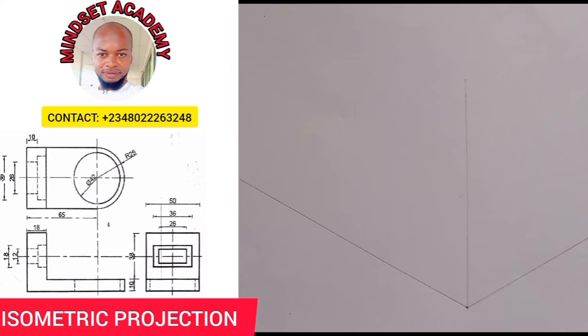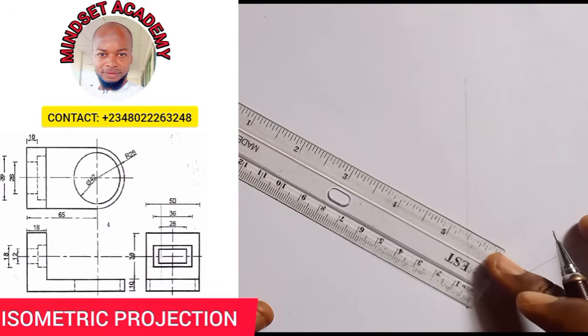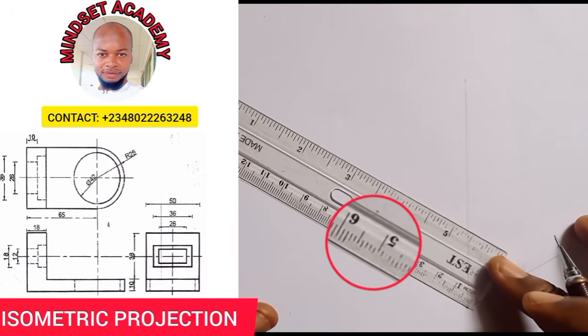The one on top of the elevation is the plan. The length from the beginning of this point to this point is given as 65. Then the radius of this arc is 25. So 65 plus 25 is 90. So I am going to measure 90 from this point, 0 to 90.